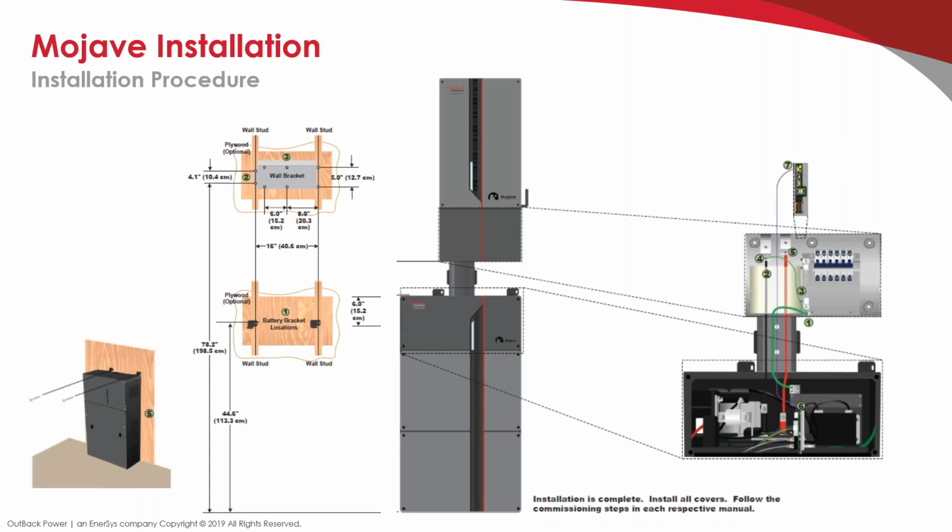Just one more thing: the example that you see in this slide is designed for the inverter to be mounted 6 inches above the battery. So the wiring kit that you see here, the battery conductors and the ground wire, has all been cut to length for exactly this 6-inch spacing.